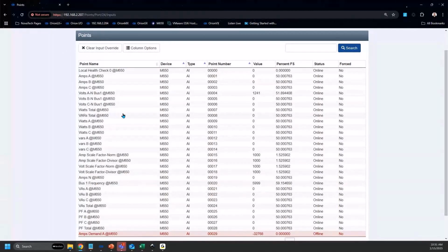I pick these, one, because they're relevant pieces of data, but two, also because you can tell it's pretty clear what these values should be. If volts are reporting 1,239 through SCADA, you know that in actuality it's 124.1 volts. And down here you can be certain that the frequency is actually 59.99. So we know what these values are supposed to be, and we see how they've come across SCADA as integer values. And you can see now that making these the values they're supposed to be, the true engineering values, it's just a matter of moving the decimal point.